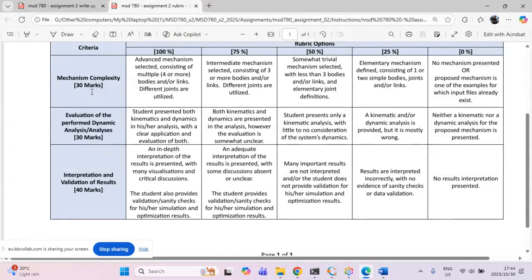But once you found your optimum design or your optimized solution, I want you to go one step further and consider the reaction forces in the system as well. See, if I now have a maximum acceleration, what are the reaction forces at the revolute joints at the wheels? And how does this compare to the initial design that I gave in? Just to have some comparison between an initial design and the final design.